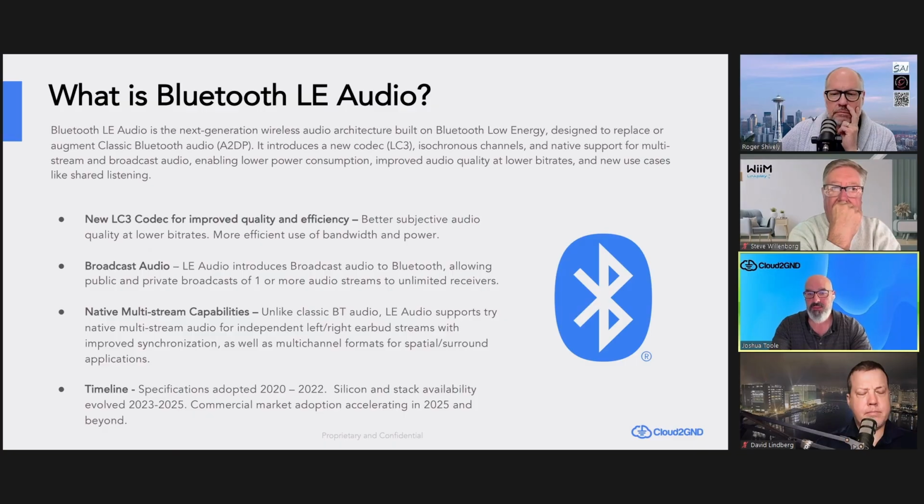And then a new standard was introduced called Bluetooth LE. Bluetooth LE is essentially a new radio architecture. It uses a fully new radio physical layer, and was initially designed really with a focus on, LE stands for low energy use cases with Bluetooth. So this was primarily sensors, fitness devices, things like that. LE continued to gain momentum, and there was a demand to look at using the LE physical layer, the LE radio for audio.